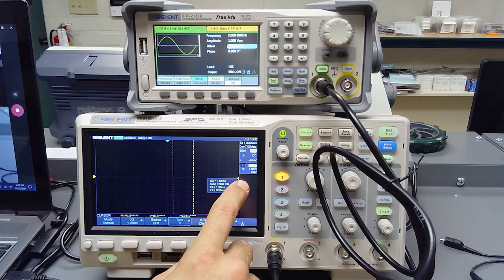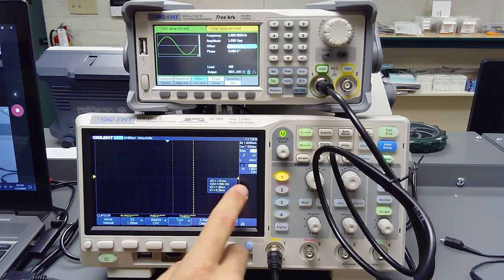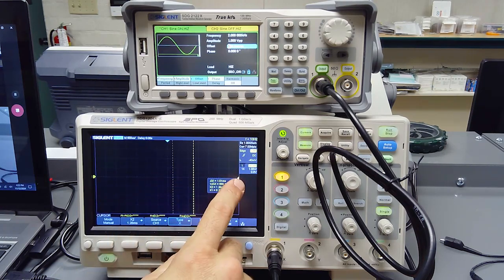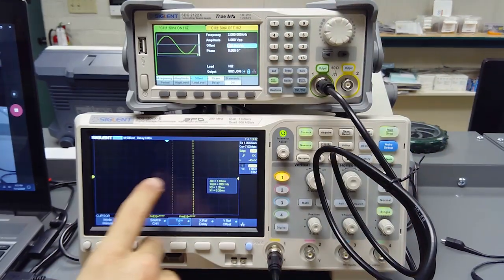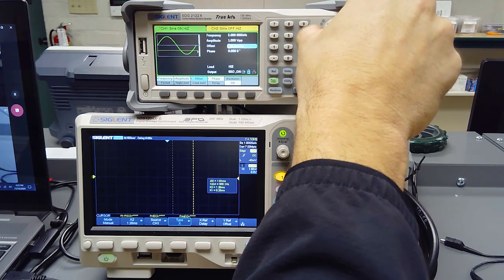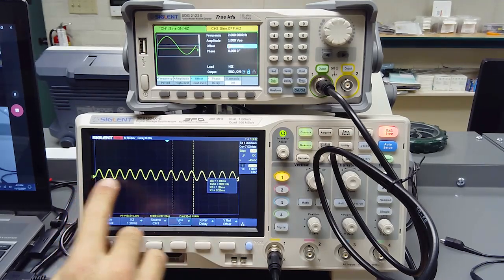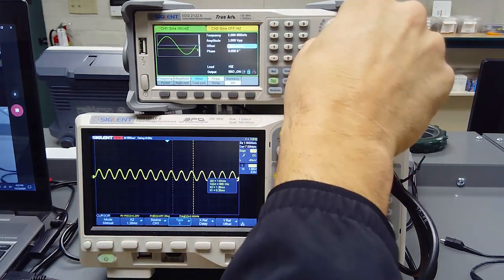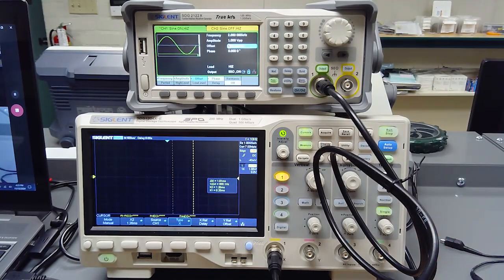So right now it's set to 0 volts. And since the signal just basically gets almost down to 0 volts and doesn't cross that line anymore, it's not triggering. When we had this going below 0 volts, it was triggering on that. So if I move this offset again, see, now it triggered because this line goes below 0 volts. Let me move this back up to half a volt and hit single again. And again, it's just sitting there, not triggering. So what we can do is move this level up a little bit.